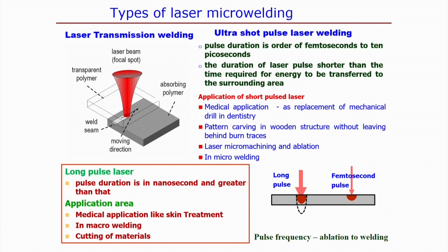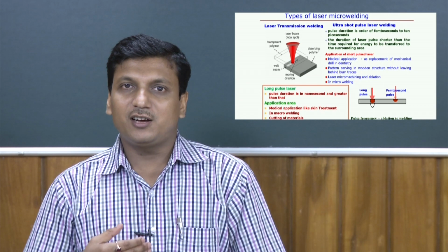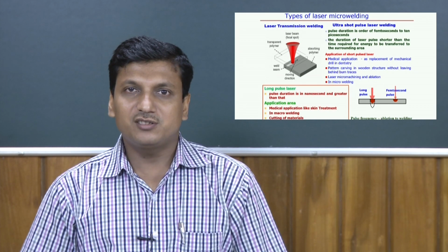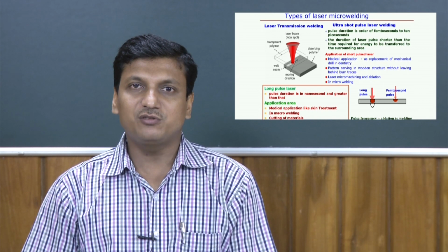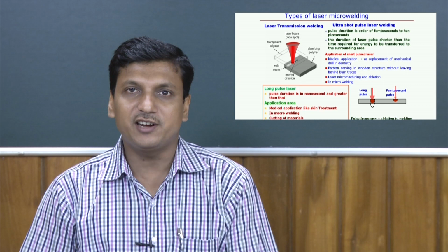This can be characterized by relaxation times: relaxation time in terms of the development of the temperature gradient within the substrate material, or relaxation time in terms of the development of the heat flux within the substrate material, which can also be delayed.